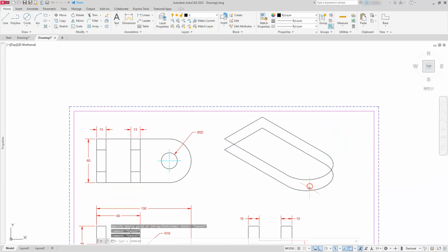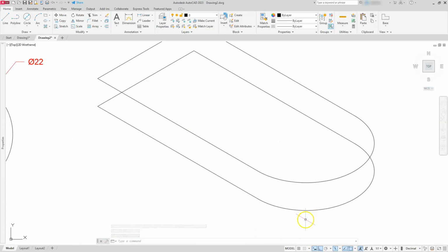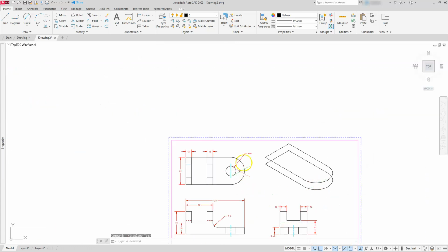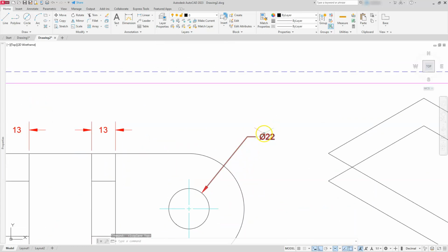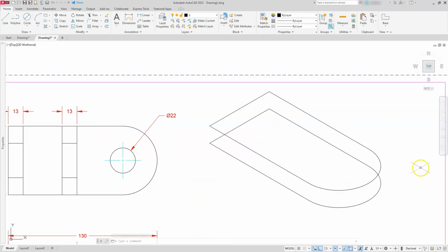Now I probably should have put the circle that's located on the center of that, and I think I'll do that now. So let's go ahead and create another ellipse. The first thing I'm going to do is go back to ISO top. Then let's make sure we know our radius or diameter. In this case, 22 is our diameter. I have to type in EL. Enter. The ISO circle. I'm going to go to this center.